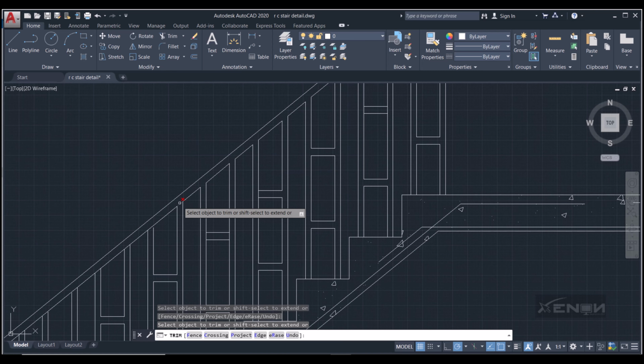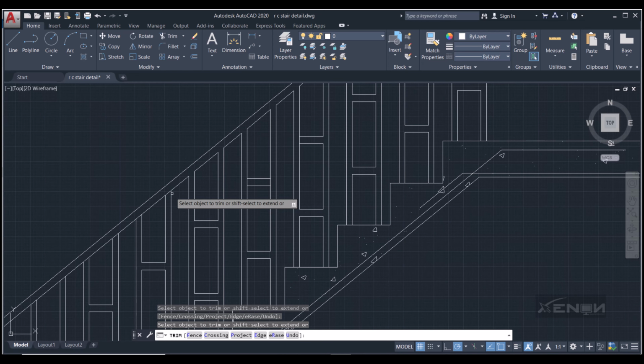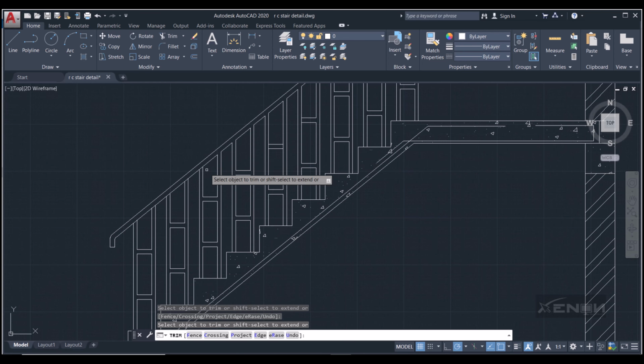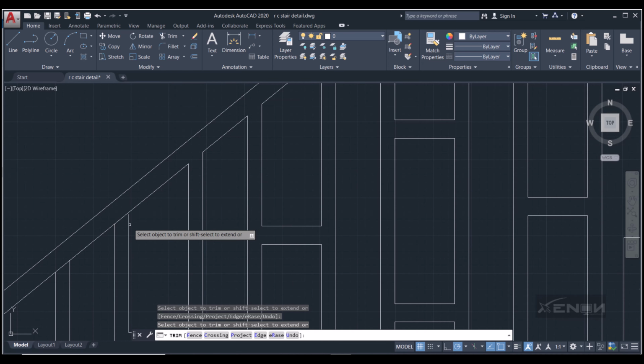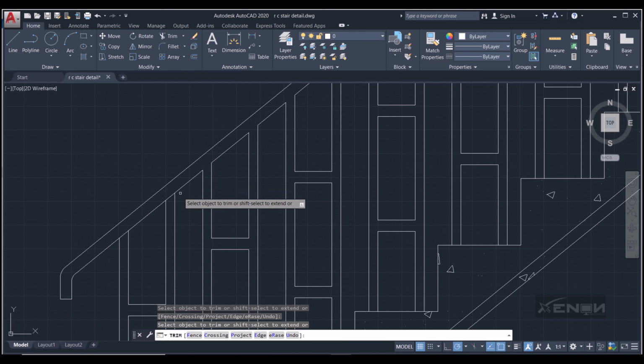Guys, if I'm fast, please pause the video and watch. Try to rewind what I'm trying to do here. I don't want this tutorial to be too long. So extend this now by holding shift and trim, extend this and trim, and trim, and finally trim.